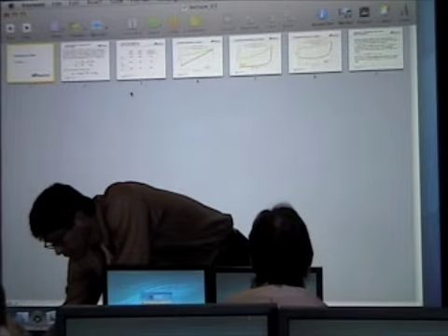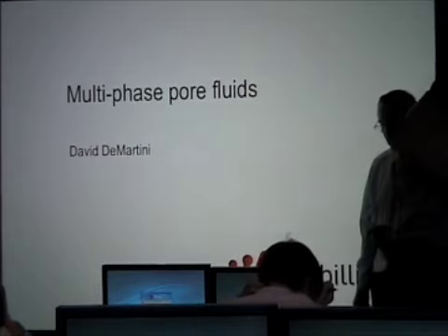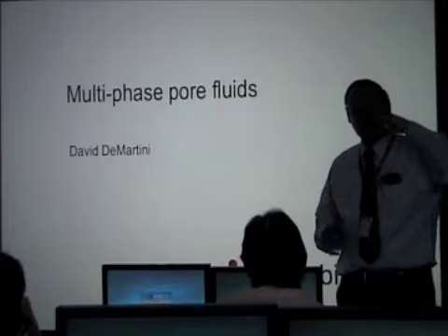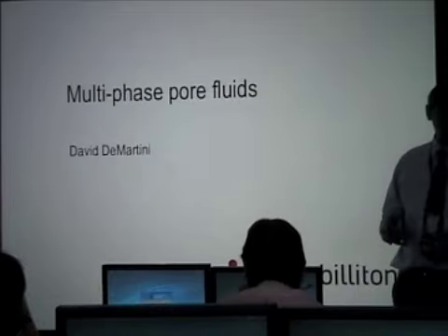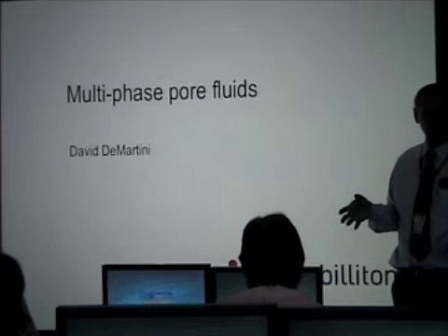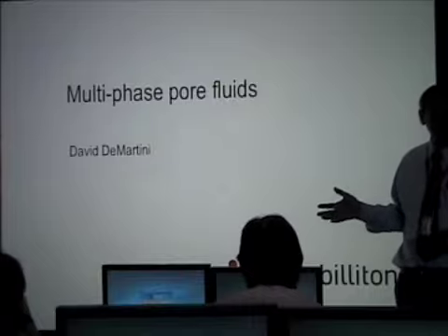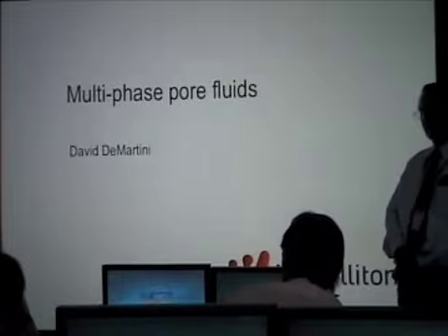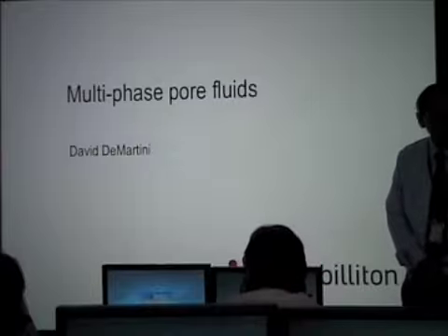We're going to look at actual properties in a moment, but the answer is, I use gas here because it's sort of the extreme case. And so you should think of that as bounding. Oil, as you know, has densities that are closer to water, typically something like 0.7, 0.8 in that range. And it turns out bulk moduli that are like 1 as opposed to 2.5 or 3 for water in some units. So you wind up with significantly less effects in oil, but still the same character of effect.